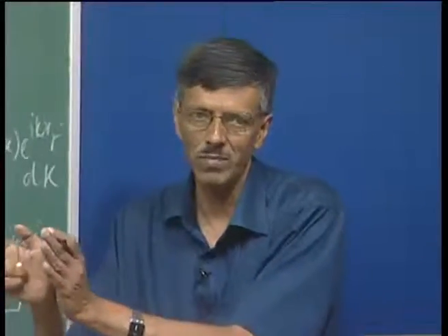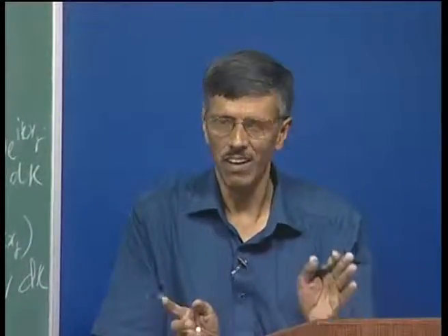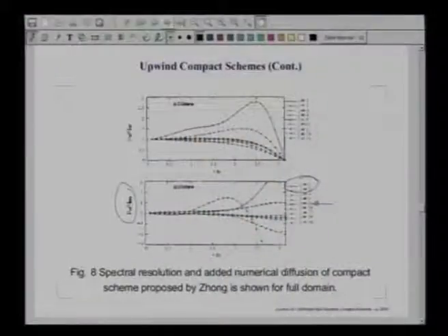This is a very typical case. Numerical instability excites the flow at the inflow, and those disturbances convect downstream and become quiet, and then we claim we have done a direct simulation of the flow. It is not quite right, but we will not go into that for the time being. But what we are noticing here is that this scheme has a spurious excitation at the inflow, that may not be a physical problem.